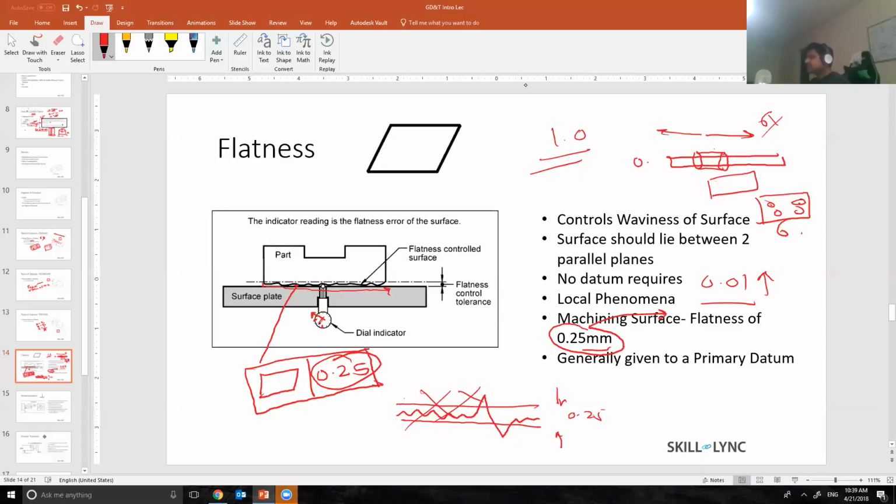In this lecture, we are just going with a very simple bracket that needs to be attached to another fixture. So I said that we need to constrain 6 degrees of freedom. But yes, in real life, based on the function, you don't need to constrain all 6 degrees of freedom. Okay, all right. Thank you so much.